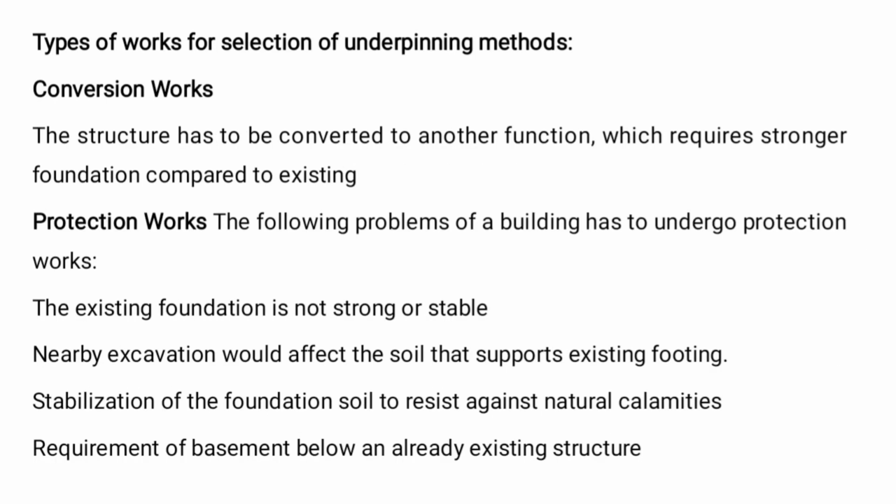The types of work for underpinning methods are conversion work and protection work. Conversion work converts the function to another function, which requires a stronger foundation compared to the existing one. Protection work is needed when the existing foundation is not strong or stable, or when nearby excavation would affect the soil that supports the existing footing, or for stabilization of the foundation soil to resist natural calamities.